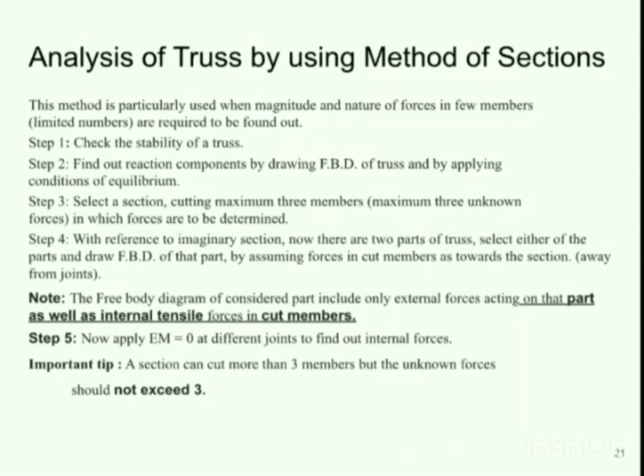By assuming forces in the cut members as acting away from the joint, towards the section line, as we had assumed in the previous slides for analyzing the truss by method of joints. We had assumed all the forces to act away from the joint. So in this method of sections also we need to assume that the forces are acting away from the joint. That means the members are carrying tensile force.